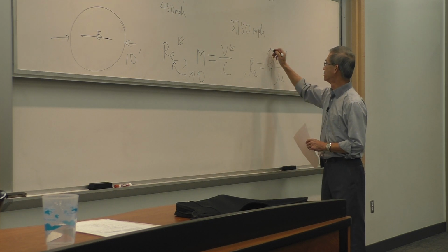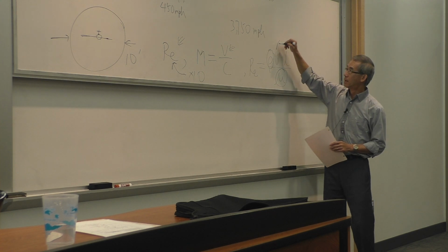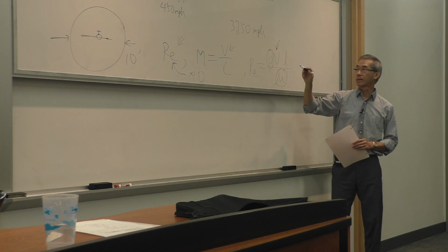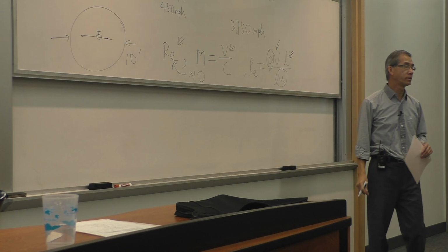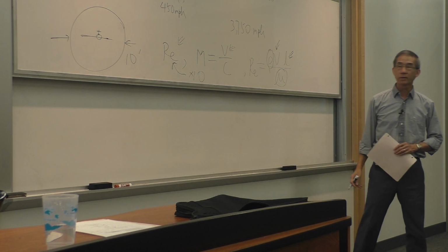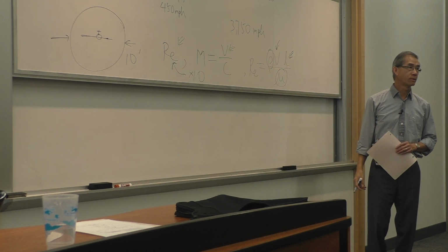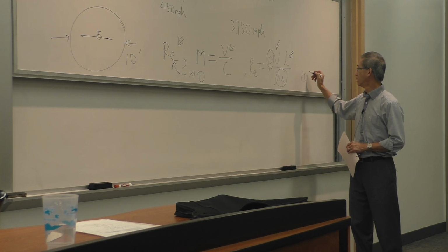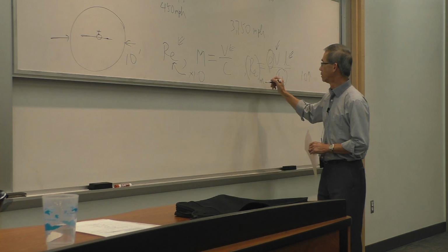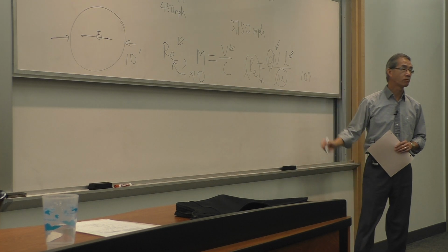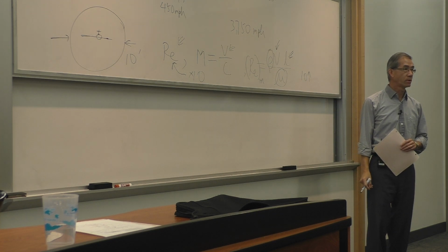What can you change? And I'll give you the answer. Velocity is bound by the Mach number. This is how big my wind tunnel is. The model is just enough to fit in the wind tunnel. What can I change in order to achieve a factor of 10 increase in my model wind tunnel testing by altering density and viscosity? Do you understand my question?